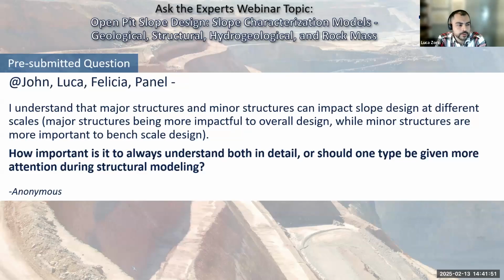And that ties up with a comment or question in the Q&A session about how we can predict shear zones and fault zones, what is the method. Well, the most advanced method is actually doing your mapping and your interpretation using major and secondary structure, because that will give you the entire overall idea of the structural pattern, the geometrical relationship.